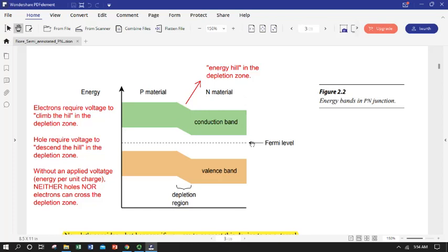Okay, the most important thing we're going to look at here is that Fermi level. That was the energy at which we had a 50% chance of encountering an electron, and electrons populate from the bottom. Now we're going to think of that Fermi level as kind of like sea level, or water leveling itself between two ponds. This is always going to be flat. Electrons are basically going to level themselves so that anywhere in the device we have equal probability.